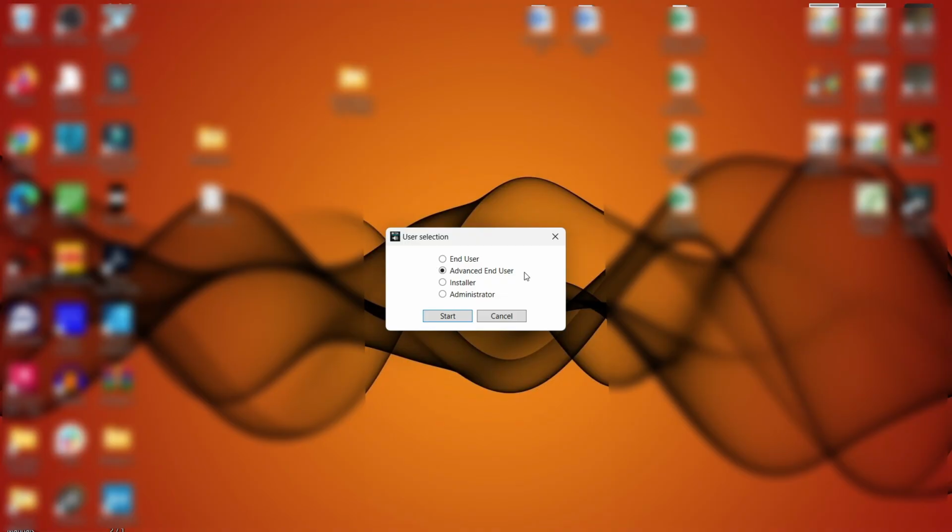Now going a step above that, you have the installer. For the installer, this is, yes, as it sounds like, typically for on-site configuration. So what you can do with this, you have all advanced end user functionality. You can configure unit connections, add, remove frames, microphones, channel panel, microphones or control panels. You can set broadcast and control output settings as well. You could assign zone patterns and priorities. You can perform simple system installations.